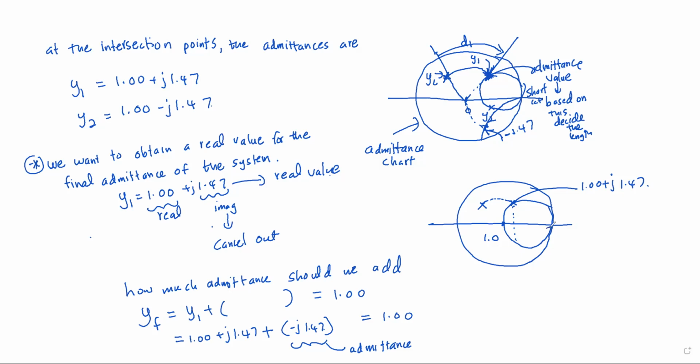So we are finding that admittance value, which is somewhere along a line in this Smith chart, and you can find the admittance values' intersecting point. It could be somewhere along this line. It doesn't necessarily need to be on the unit circle. It can be somewhere along this line in the bottom part of the Smith chart.